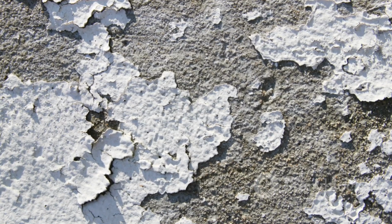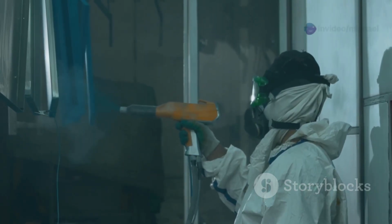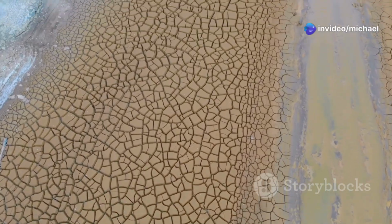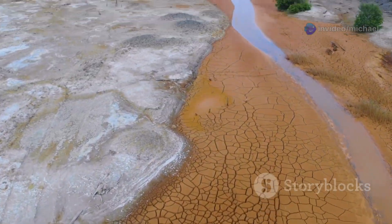Think about applying too much paint on that wall. It'll drip, sag, and maybe even bubble. Same goes for coatings. Too thick, and it's a recipe for disaster. The outer layer dries before the inner layer, trapping solvents and causing, you guessed it, blisters.